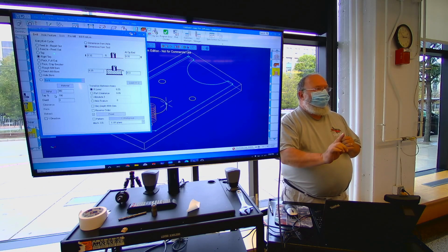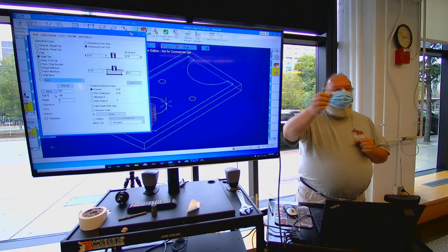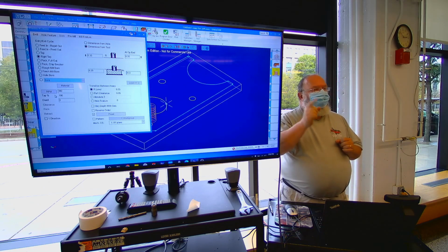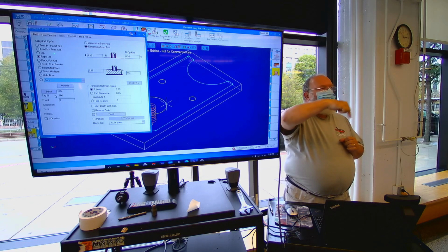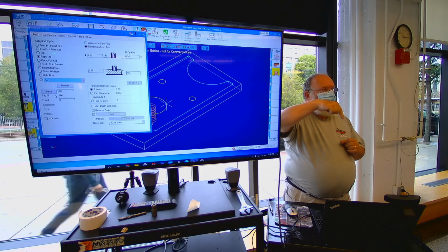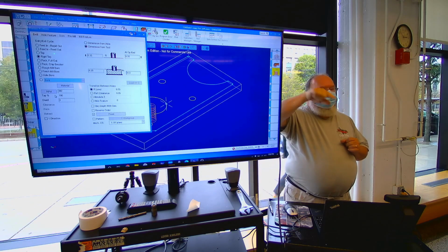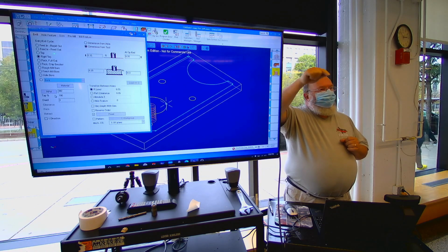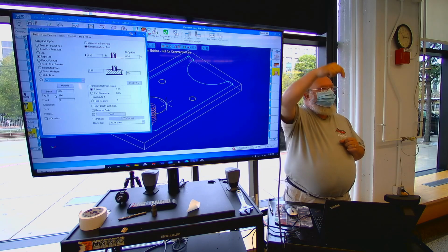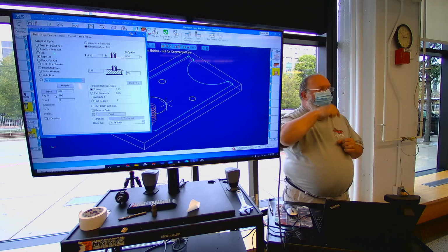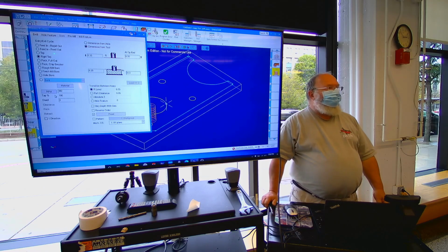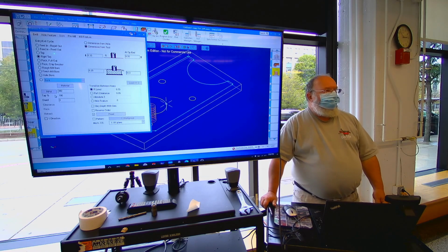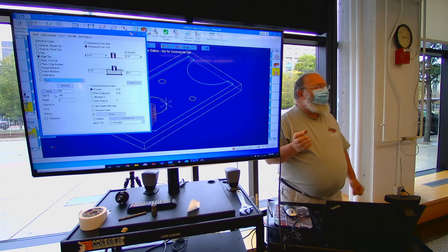Following me? In order to hold a tap rigidly in that spindle, the machine has to match the RPM speed with the linear travel per revolution. Okay? So every revolution, it has to feed my 20 pitch thread 50 thousandths deep. Okay? And then we come to the bottom. So what happens in the bottom? It has to stop, right?